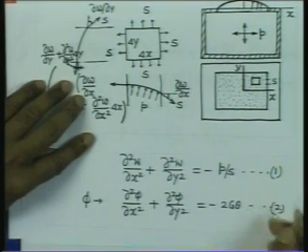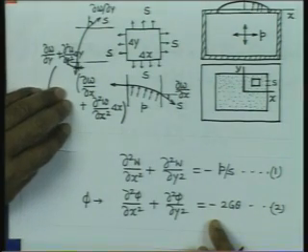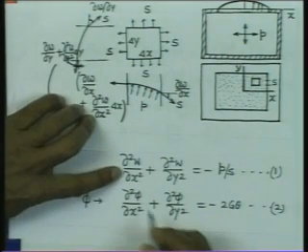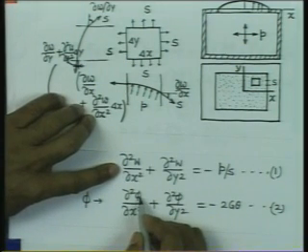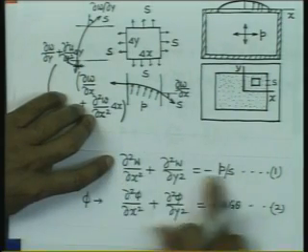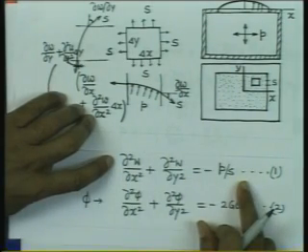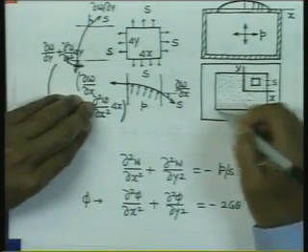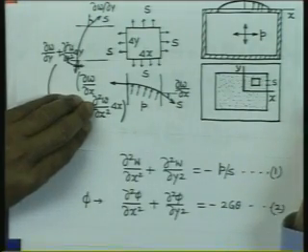So, these two equations are analogous, and therefore, it is possible to get an idea about the function phi by looking into the deflection of the membrane, provided the geometry of the membrane boundary corresponds to that of the shaft that one is interested in.